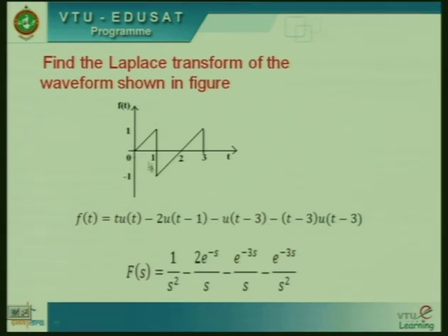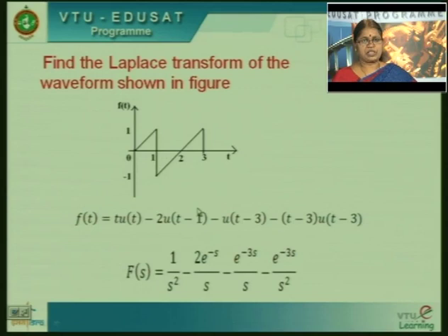So, I need to bring the signal to have a change at time t equal to 1, where we are adding a unit step signal, and to bring down the signal value to 0 at time t equal to 3, we need to add a ramp signal and a step signal.